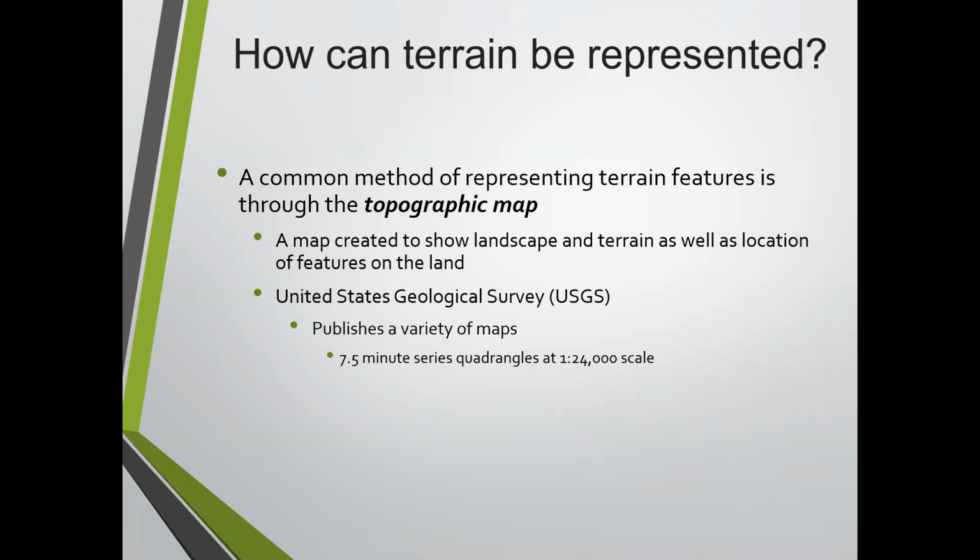And the scale 1 to 24,000, that's a natural scale, so that correlates with a scale of 1 inch equals 2,000 feet. So this is a pretty small scale map. They also distributed them in smaller scales even. The other scale that was commonly used was called a 15-minute quadrangle, and that was at a 1 to 50,000 scale. Not too many people use those, but a lot of people use the 24,000 scale.